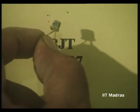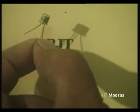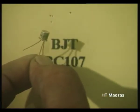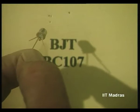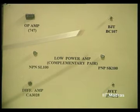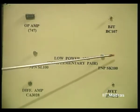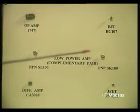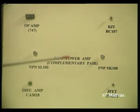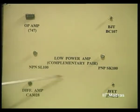And you can also identify the base. Base forms a triangle, and the base is the center, or the apex of the triangle, and the other terminal is the collector. That is how you can identify emitter, base, collector of a transistor. These 2 are an NPN and PNP pair, which are commonly used for power applications, which we will see later. This is called a complementary pair, NPN PNP pair. These are used in low power amplifier applications.